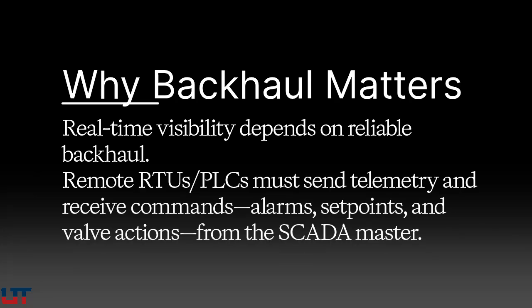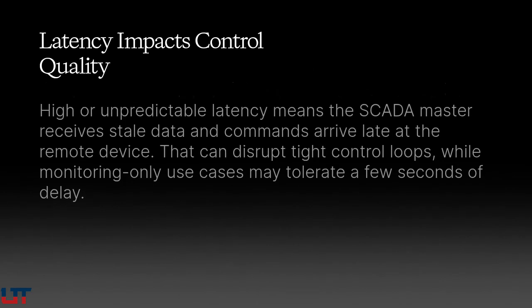Operators at a central control center need real-time visibility across dozens or hundreds of remote sites. RTUs and PLCs at those sites must send back data to the SCADA master and receive commands from it. Alarm conditions, set point changes, valve commands. The quality of that communication path directly affects the quality of control.